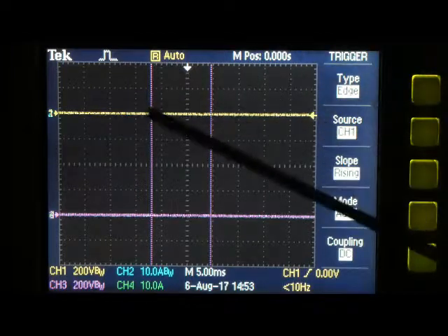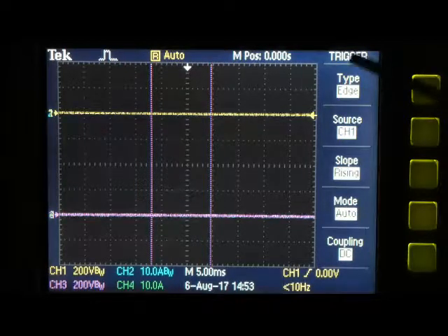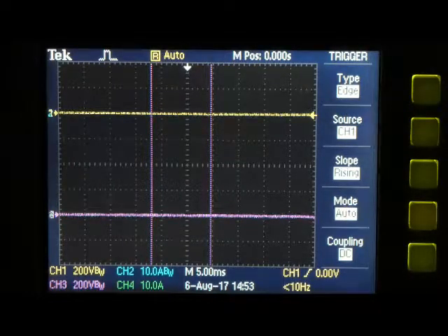Once I turn the inverter on, it will bring its output up to 230 volts for 10 seconds to power the grid interface, and the grid interface will check to see whether there is any voltage coming in on the grid connection. When it finds there isn't, the inverter will quickly turn its output down, connect the inverter through to the house circuits, then ramp the voltage up again.